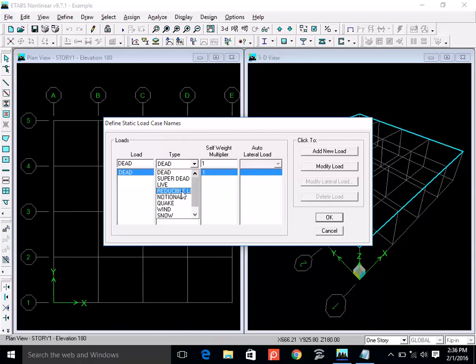So instead of saying that the entire area would be loaded, we reduce it maybe 85% or 90%, maybe 75%, and we call it reduced live load. There is a formula which is used to reduce the live load, but for smaller structures you can continue with the live load, don't reduce it.